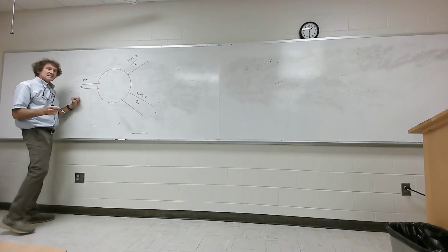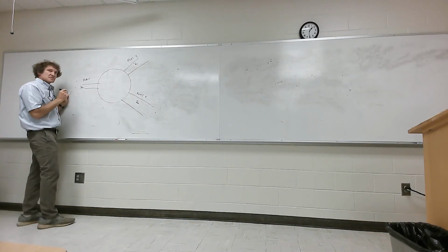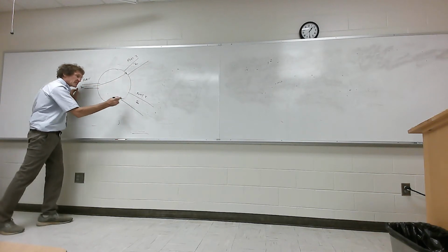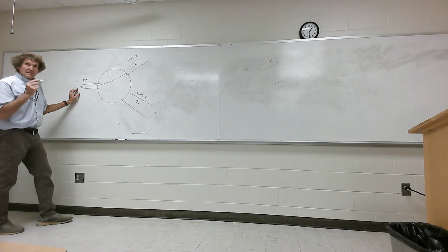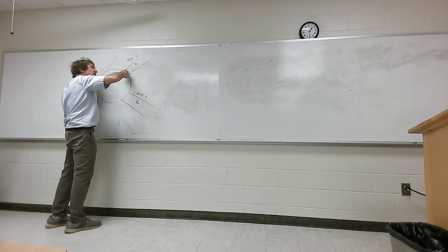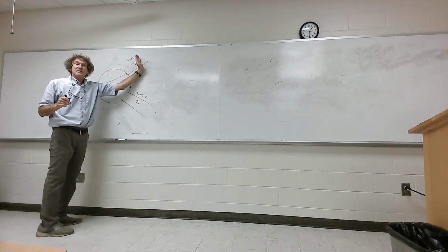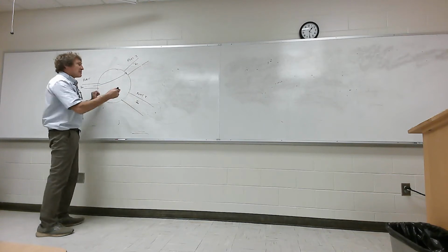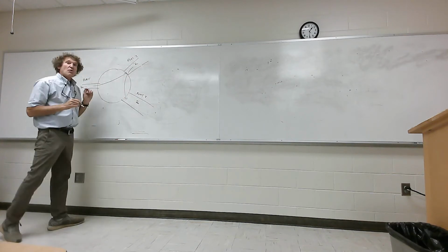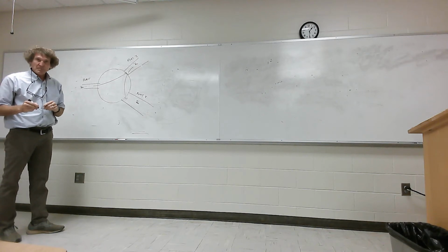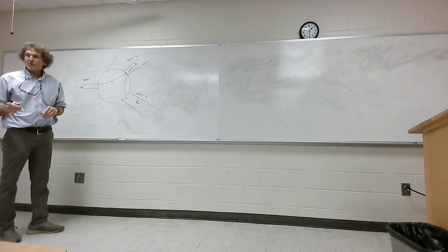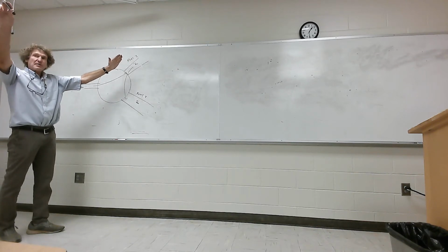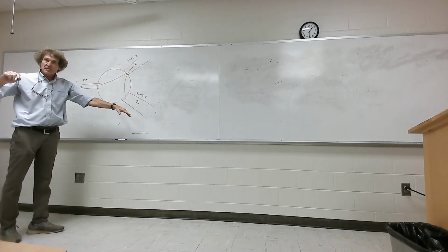Okay, now here's the deal. For port 1, assume this is a power source. He wants all of that to go to that port, and none of it to go to this port. And then he wants any signal received at this port, so think of this as your antenna, everything that's transmitted he wants launched, and anything that comes back he wants only to feed into port 2. That usually is as far as it gets, and that's a transceiver. Everything launched this way is thrown out, anything coming back this way goes to port 2.